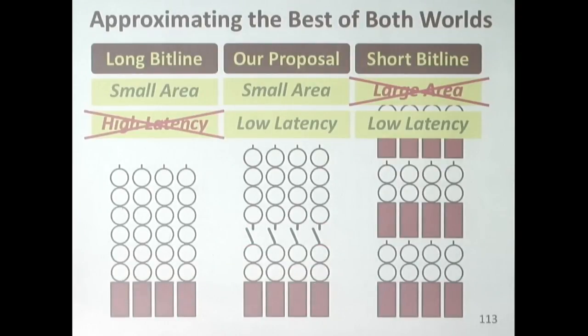The idea is you don't have a perfect bit line, but you can actually turn off part of the bit line. If you turn off this part of the bit line by disconnecting the top portion from the bottom portion by isolating it, now this part looks like this, right? The sense amplifier sees only a short bit line. And that's the idea over here.